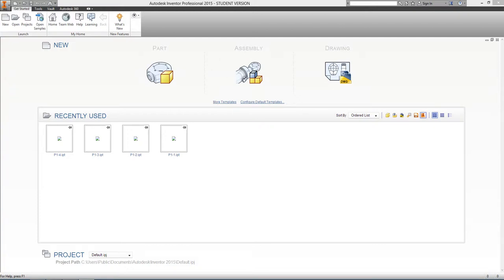For exercise P2-7, we're really going to focus on what parametric feature-based modeling means. It's important to first look at the exercise and determine how we want to do this. I can see that there's two big fillets and a flat oval with a little cutout at the top. So the main thing that I want to focus on is what in here can I do as a secondary extruded feature, what can I do as a pick and place feature, and what is the sketch that I can accomplish the easiest given the object that I have.